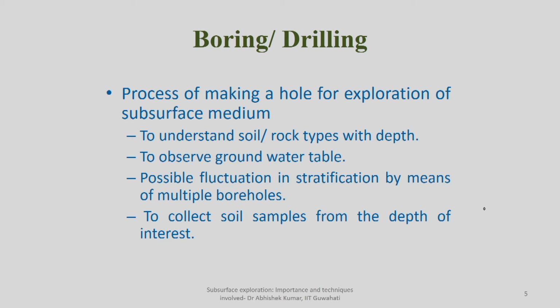You can collect the soil sample, take it to the laboratory, and identify classification, moisture content, density, Atterberg limit, strength characteristics, even consolidation behavior of the soil, if, as I mentioned earlier, you are getting a relatively intact soil sample. If you are getting a highly disturbed sample, you will only be able to identify or classify the soil, depending upon the level of disturbance imparted while collection. If it is more disturbed, you will not be able to use it for shear strength characteristics, because that is not a true indication of the state the soil exists in at the site of interest.